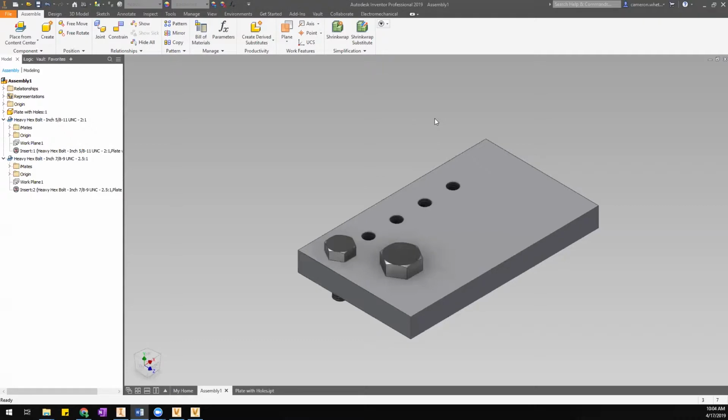Decide ahead of time, think ahead about what you want to do and how you're going to do it, so you can make sure that you're doing things in a consistent way, keep things organized, because depending on what your needs are for content center, you could potentially end up with thousands and thousands of new parts and families, and over time your content center can get quite large and, if you don't keep it organized, it can become really difficult to manage.